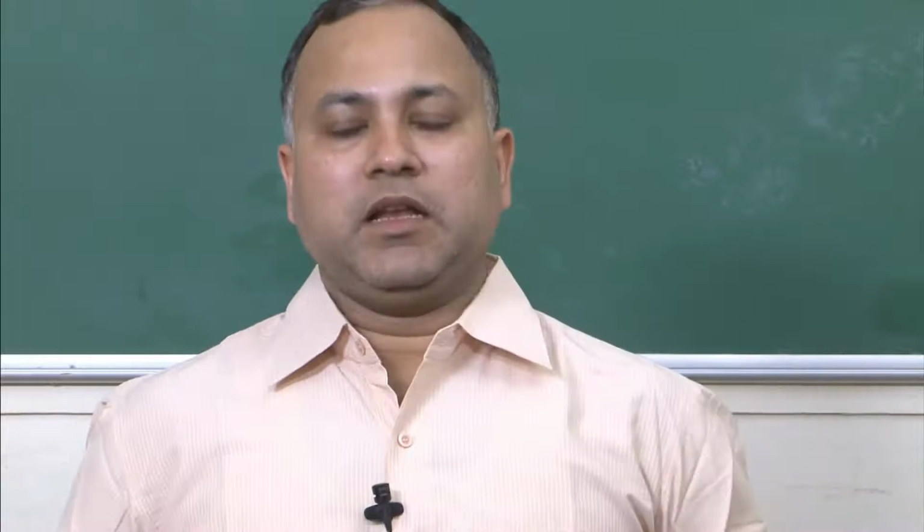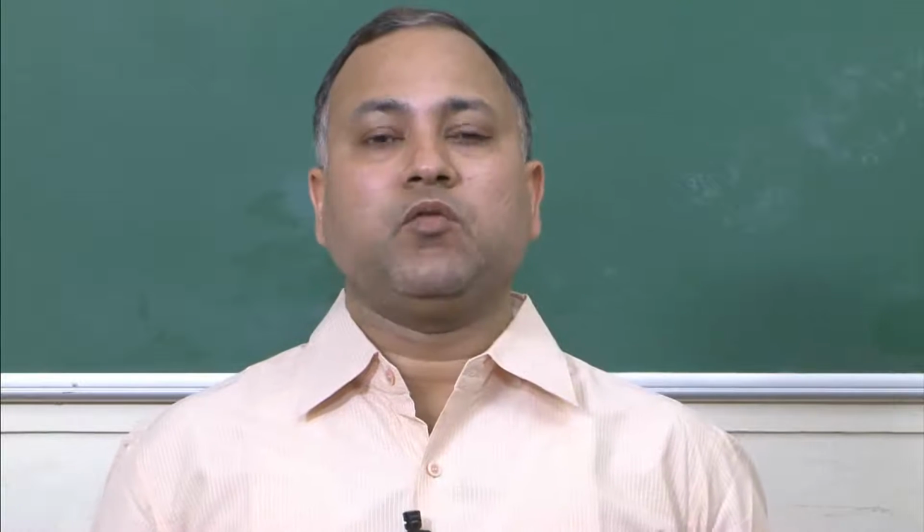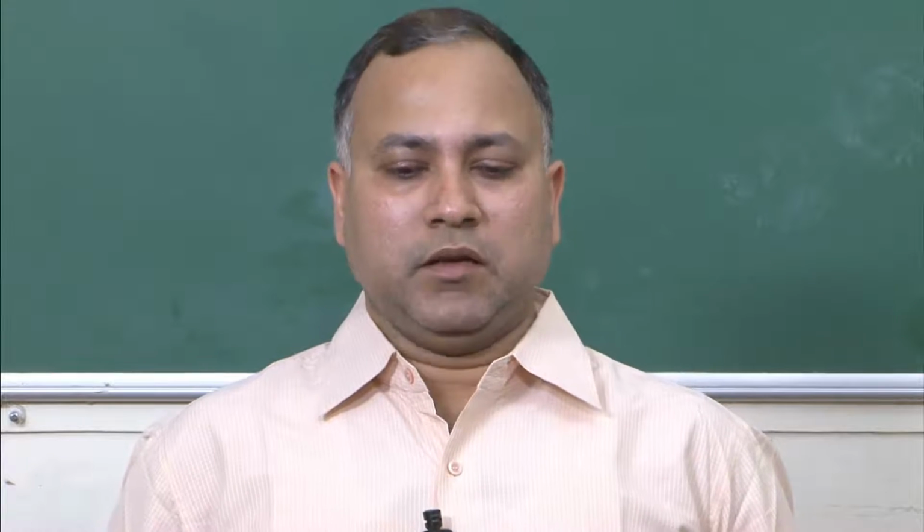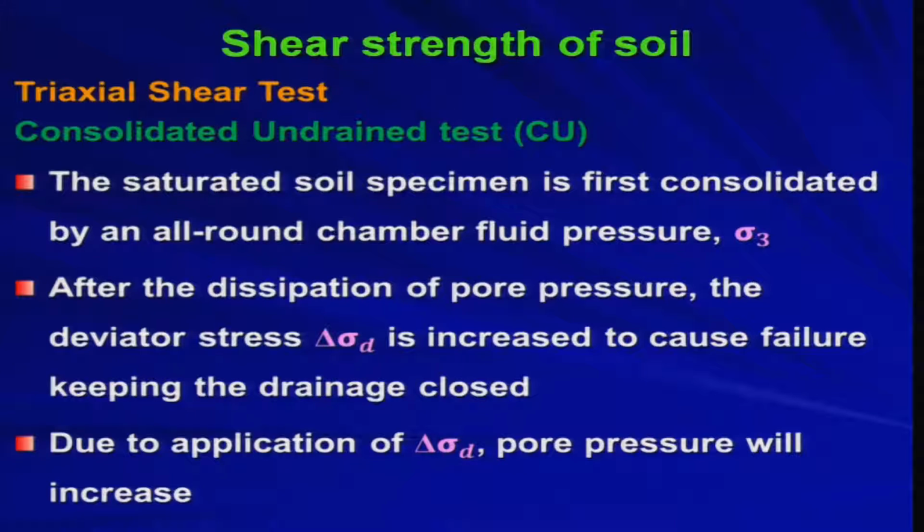Welcome back. In the last lecture we were discussing the consolidated drained triaxial test, and we saw the different issues associated with it. At the end we concluded that the consolidated drained test is time consuming, and therefore it is not very popular in the community of geotechnical engineering. Therefore, the second type of triaxial test.